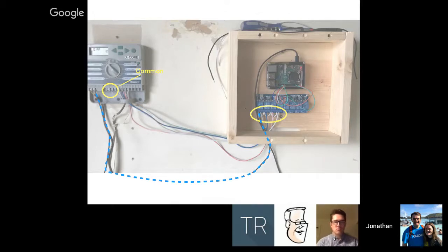My controller zones were clearly labeled. Like, it's really blurry, but where that circle common wire is, there's actually a C, and then all the other wires are 1, 2, 3, and 4. So they're pretty easy. I did have to get a multimeter though to test which one of these split lines, like the end of this blue line into my controller, was connected to common versus just the hot wire. But it was pretty easy.